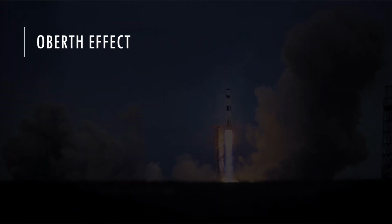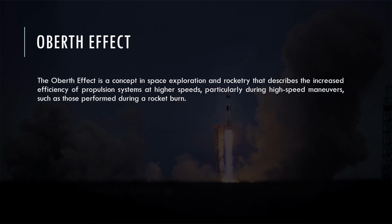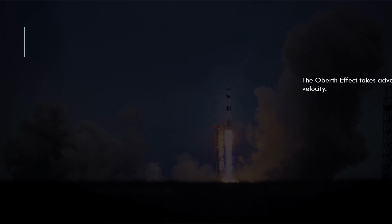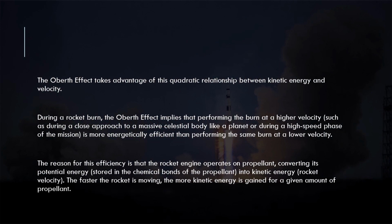Here we come to our next method, which is the Oberth effect. The Oberth effect is a principle in astronautics that states the efficiency of a rocket's propulsion system is maximized during powered maneuvers at higher speed. According to the Oberth effect, the energy gained during a rocket burn is directly proportional to the velocity of the rocket. Therefore, performing maneuvers such as the propulsion burn at higher speed results in more efficient and effective use of rocket energy, leading to greater overall effectiveness in changing the spacecraft trajectory.